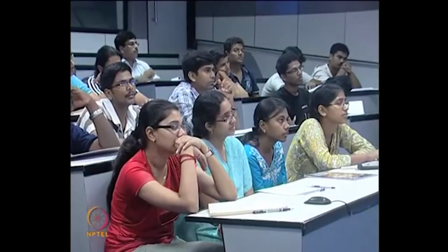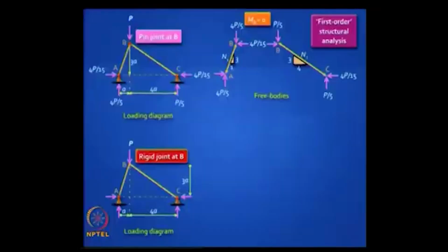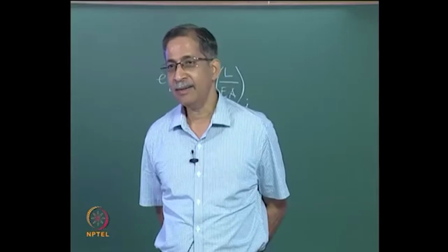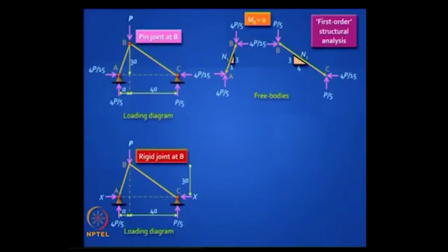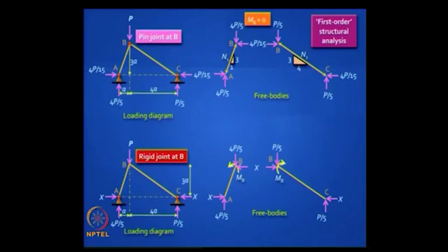You can get bending moment, because now the joint at B is rigid, which means you have a moment resisting joint, right? Now if you get a moment, the question I wish to ask you is, your vertical reactions do not change, your horizontal reaction is your unknown. If you get a moment at B, is that moment going to be sagging or hogging? I have shown here sagging.